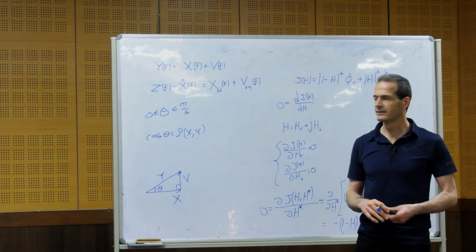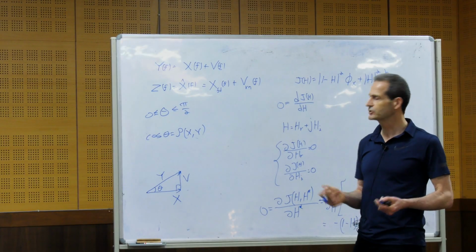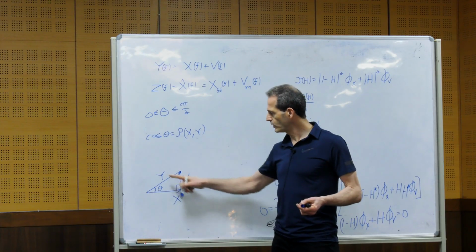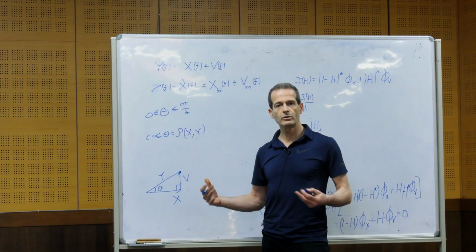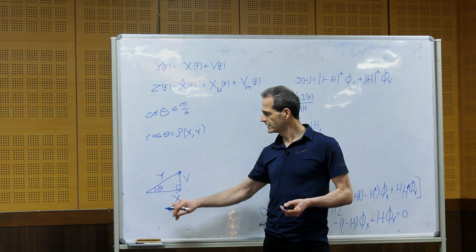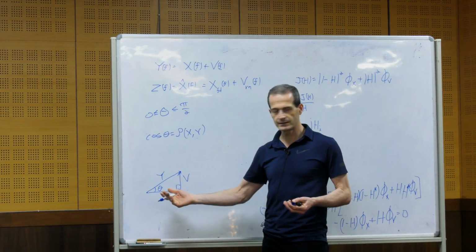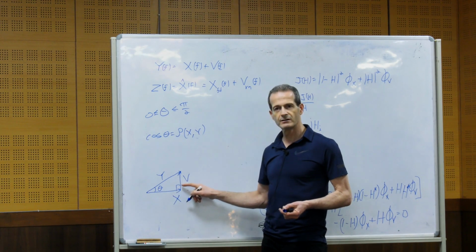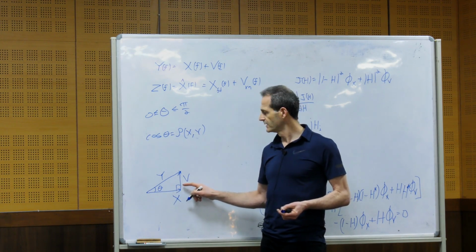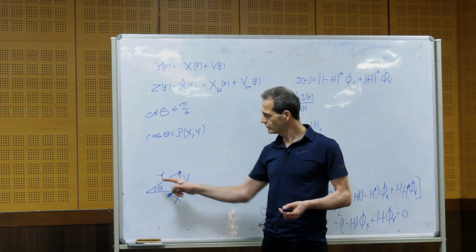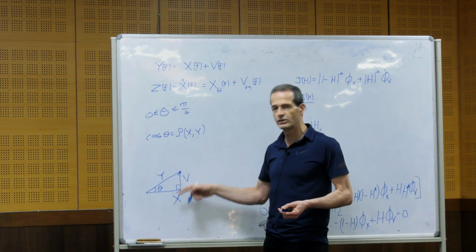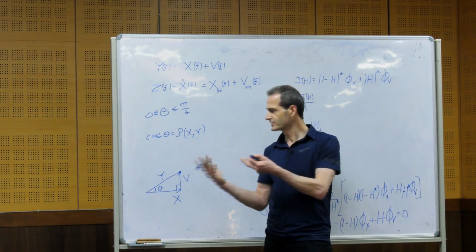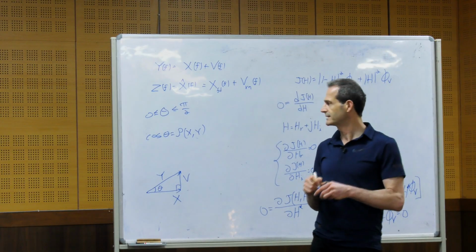And you can represent signals this way. It's more like a convention. So when theta is small, we see that y and x are more correlated. When theta is large, it means that they are less correlated. Also, when theta is small, the noise is small, so the input SNR is high. When theta is large, closer to 90 degrees, the noise is large, so the input SNR is lower. So it's a nice way to present signals.